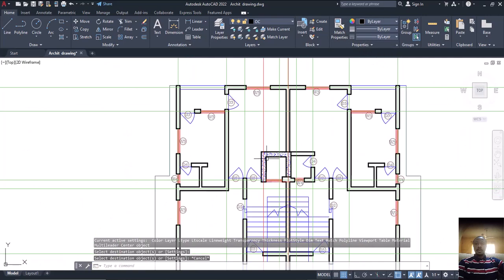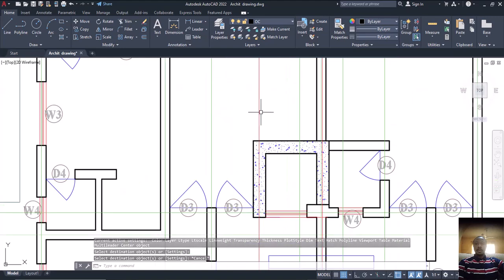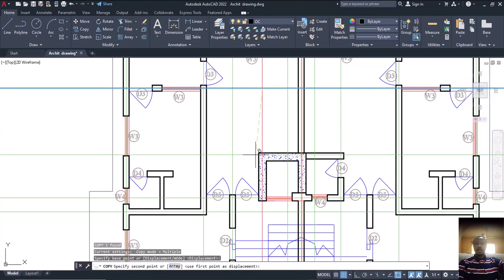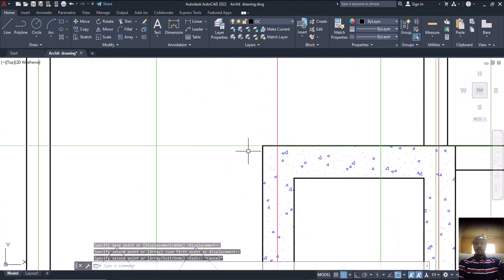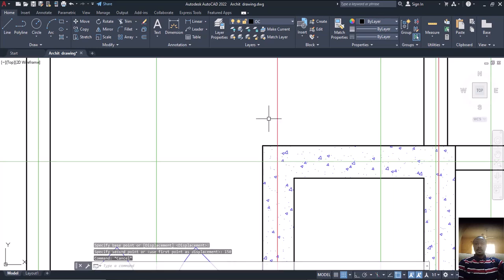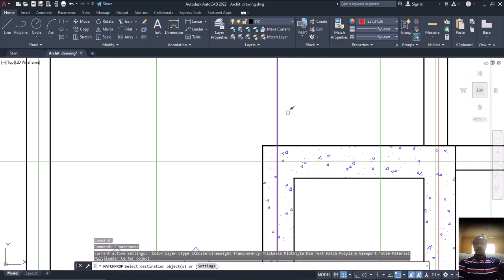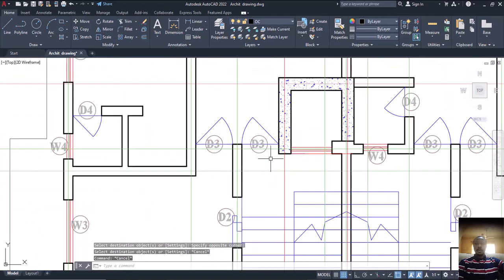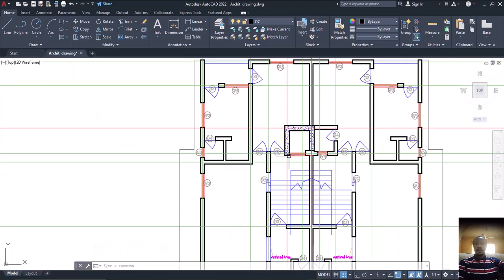And you also need one for this particular place here, isn't it? So I'll come here now, then CP, enter. From here I'll put at the edge first. Is that okay? I'll come here now, then M, enter. That's move. Come down here by 150, enter. Can you see it now? So I'll also select this one now, which stands for the wall grid line. Is that okay? This one can also work for this. So let's see.